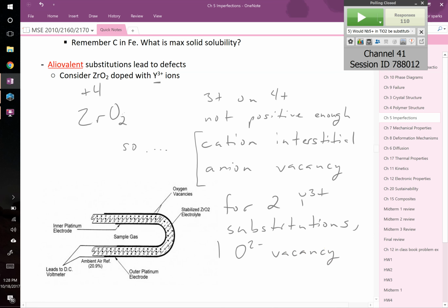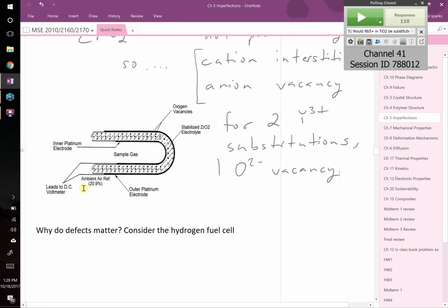How this works is you have a tiny little oxygen sensor in your effluent of the gas that's coming out of your motor, right? So the effluent, you'd hope if you mixed the right amount of fuel to air in your piston and combusted it, that you would have no oxygen left over, right? That all the oxygen, just the right amount, would combine with the fuel to form your CO2 and water vapor and other byproducts, right? But if you're running rich, and you've got too much fuel, then you've got fuel coming out left over, right? And if you're running lean, then you don't have enough fuel and you're getting excess oxygen left over.